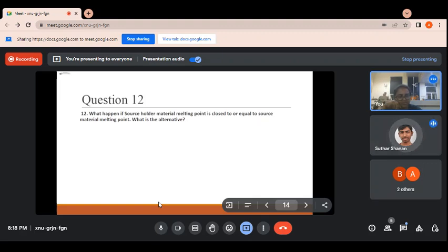Okay. So after the acetone dip, do we go for annealing, or do we go for annealing and then the acetone dip? Which is the right one? Actually, when we dip the device into the acetone, it removes the photoresist. So if you want the photoresist to remain and want to reduce its defects, then before removing the photoresist you have to use this annealing process. It depends upon the application.